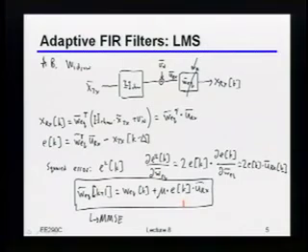Because both contain the noise, you're including the effect of the noise. If the noise was too large, your errors would also get larger, and when they got larger, you'd see they were correlated with the input of your equalizer. So this does indeed converge to the MMSE solution. Does that make sense to people?